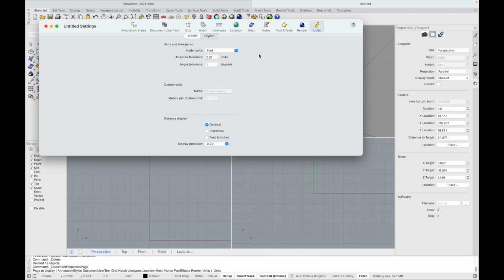So if you're in my studio or in an architecture program or whatever, which is of course the intended audience of this video, chances are the materials that you're working with are pretty small. Even if you're working at building scale, lots of little building materials are way smaller than this, because 0.01 feet is almost 1/8 of an inch. 1/8 of an inch is thicker than a lot of stuff. So if you're in an architecture studio and you're doing a bunch of stuff with 1/16 inch chipboard, 1/16 of an inch is smaller than this tolerance.